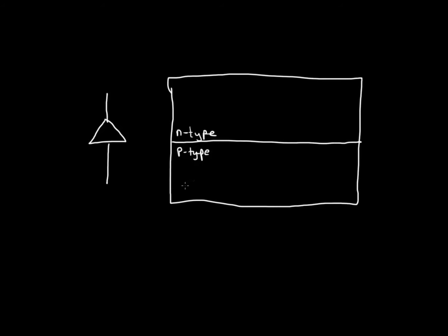Photodiodes are the most common infrared sensor too, built in different kinds of materials like mercury cadmium telluride, gallium arsenide, indium gallium arsenide. But here I'm going to focus on silicon, and use it to detect visible light. That's what's going to dominate my discussion. This photodiode, this is the basic unit for photodetectors. Not all infrared detectors use a photodiode, but most do. So I'm going to discuss the photodiode.